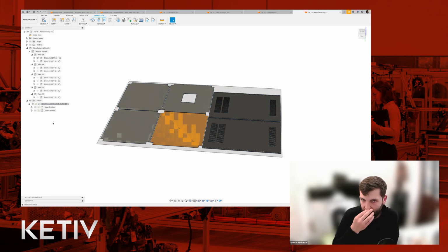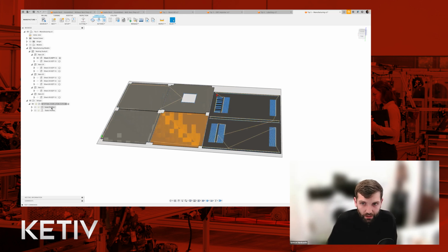So it may look like you're basically doing the toolpaths again. But all of those other settings, all of the tool information, all of that built-in intelligence is already in the template. And to create the template, let's say I programmed one of these parts now. I can select them both, right-click, store as template.